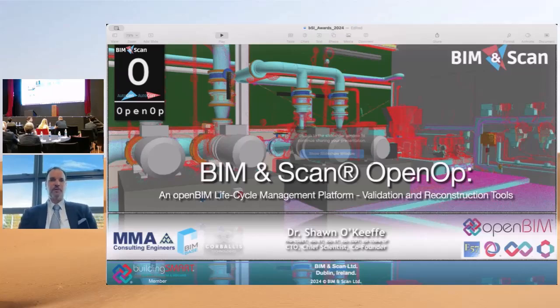To start off with, we use the IDM and MVD process thoroughly, creating BPMN models based on IDM for every single exchange within our system. There is no exchange without utilizing this process. And then I also do a value-add assessment on top of that to continue to make these processes leaner over time. This is the standard IFC software build methodology that should be deployed within all IFC-based systems.